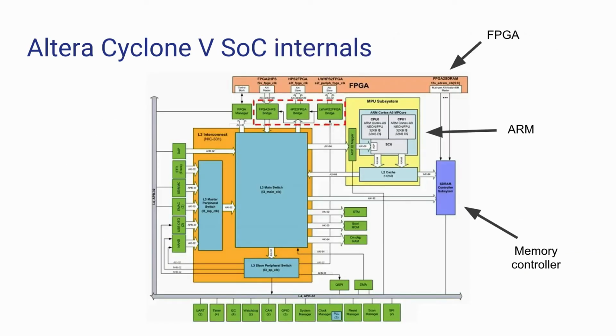This is a quick overview of the FPGA chip. Just roughly speaking, the orange part on top is the FPGA fabric itself. The green square is the ARM. This giant thing is a huge switch. So SoC stands for System on a Chip, and the idea is, for a desktop, you're fine having a CPU that's just a CPU, and you can have a bunch of other chips for Ethernet or whatever else you want to do. But if you're going to make an embedded system, you can't have these 20 chips sitting around.